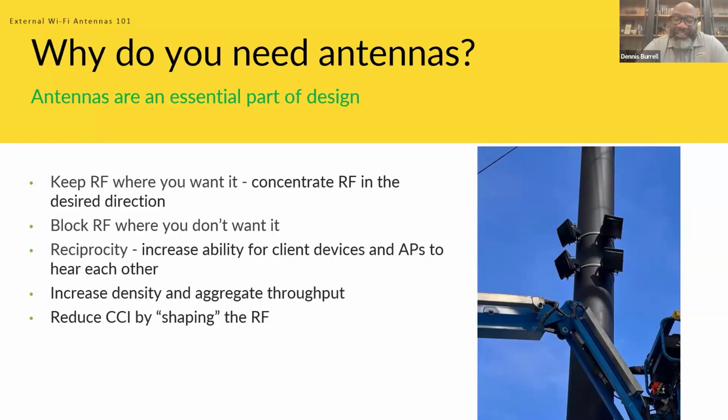That picture to the right just shows us some deployment of some high gain antennas on our colo mount. So it's a colo mount where the AP is on the back side. Then you have an antenna tray with the antenna on the front, and the antenna cables are wrapped on the back side of the tray. So it's like a seamless design. So that's just one way for external antennas in an outdoor environment.